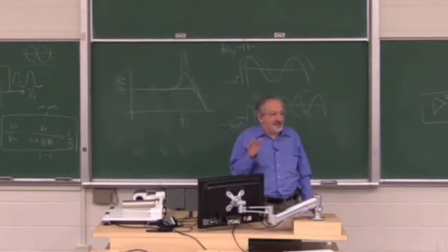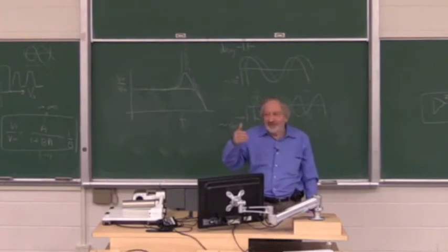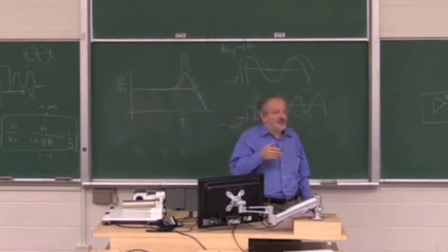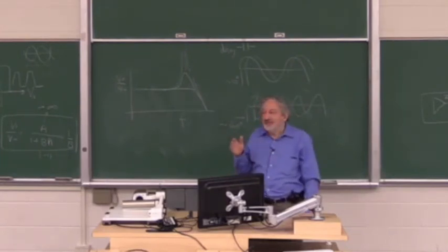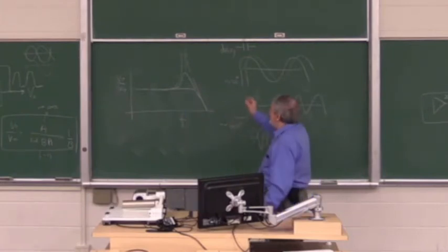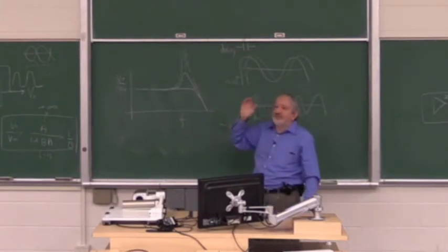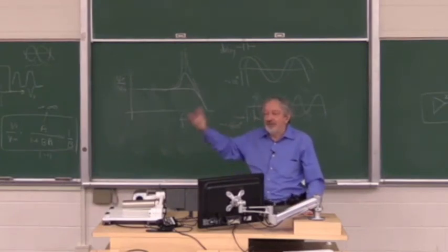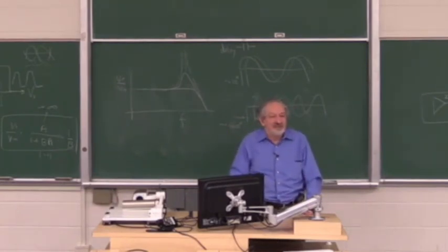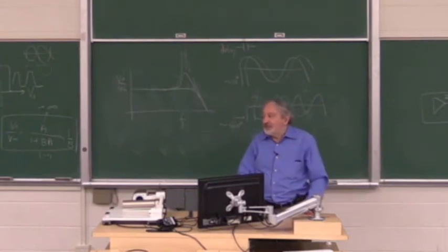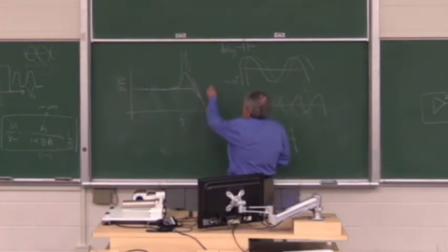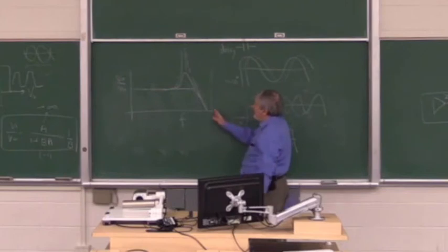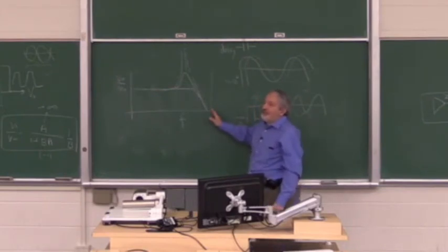Is that clear, everybody? You better stop me if it's not clear, because you wouldn't be able to follow the rest. So, is that clear why the same delay, no matter how small, at some frequency will give a 180 degrees phase shift, and then the feedback will become positive and it will oscillate? Okay? So why doesn't it oscillate here? Because here the delay will be even a bigger phase shift.